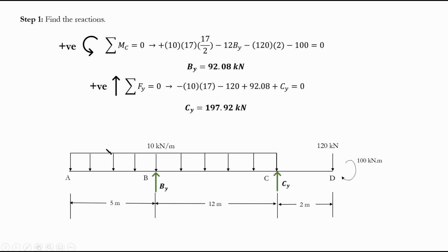And you will say, okay, let's just cut it at portion AB, right? That's what we do. Just cut at point B because this is the point I need. And again, why are we finding general equations for different portions? Because my loading changes, right?